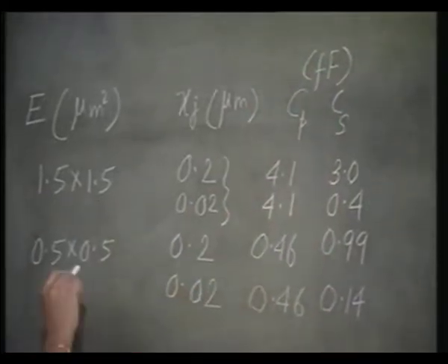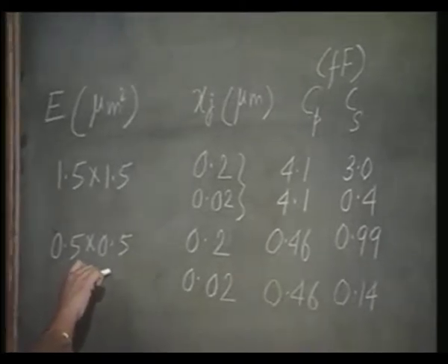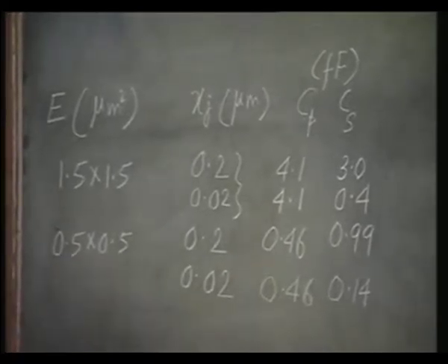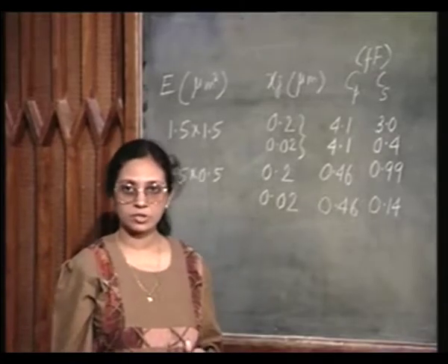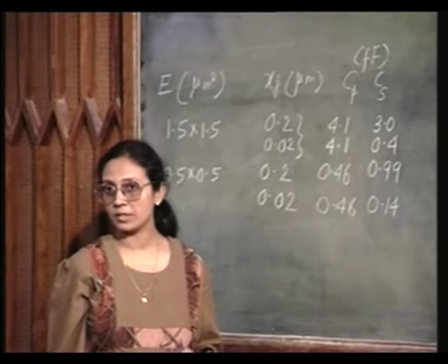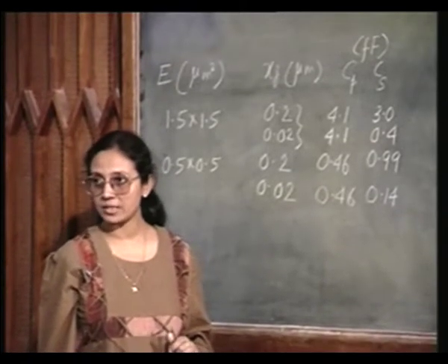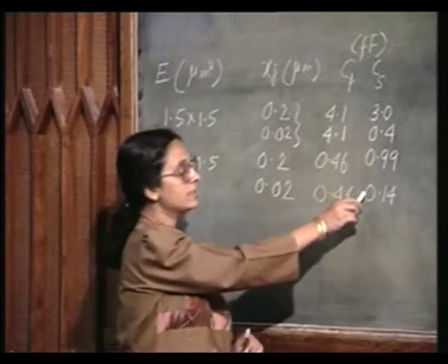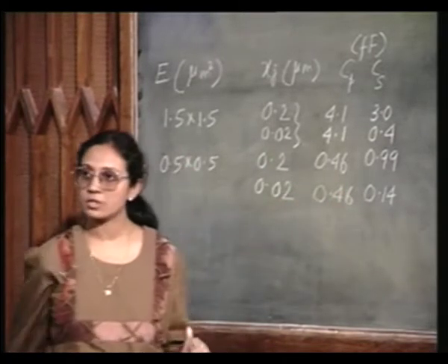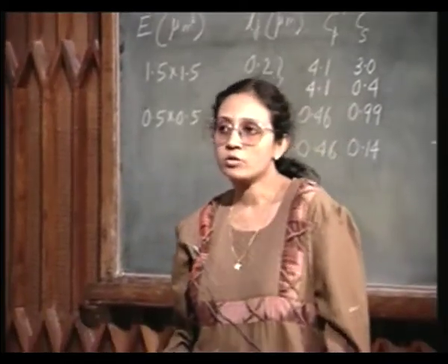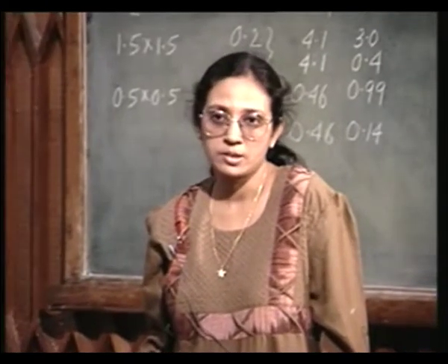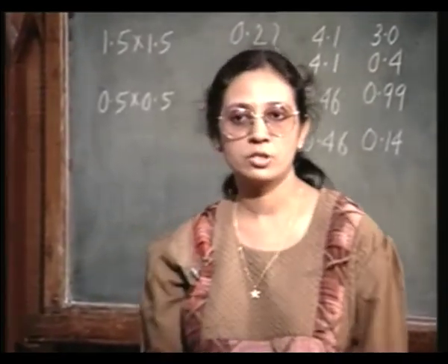So you see, this becomes very important when the emitter size is reduced. For smaller device dimensions, it is very important that not merely you reduce the device dimensions, because that is finally not going to determine the speed. It is the peripheral capacitance or the sidewall capacitance, and that can be reduced only if you reduce the junction depth. Which brings us to the important requirement of a high speed transistor: I must have shallow junctions.